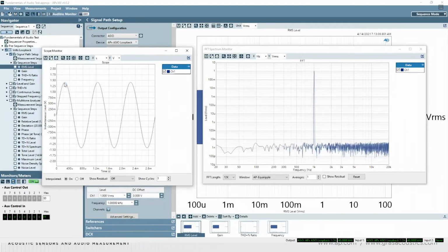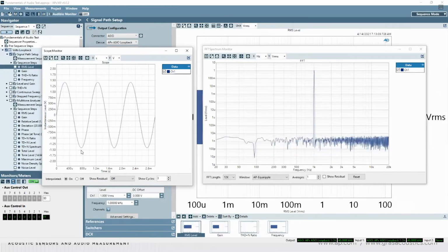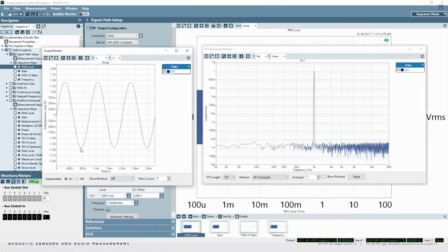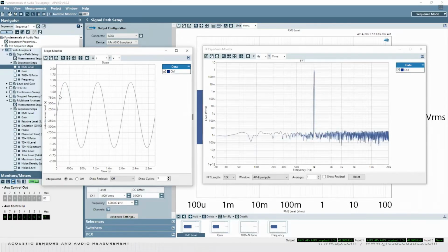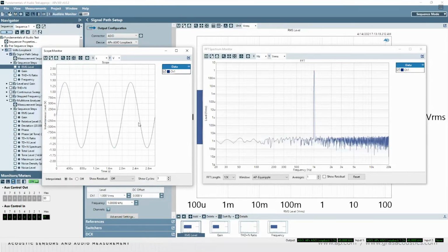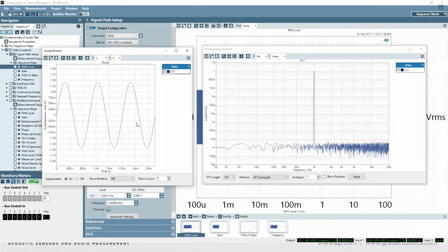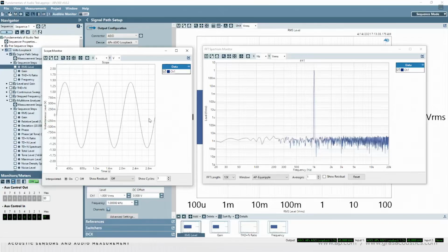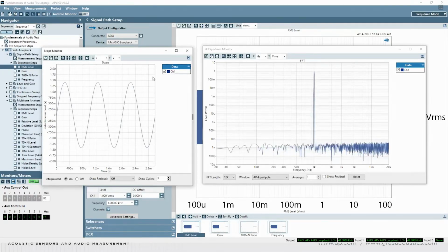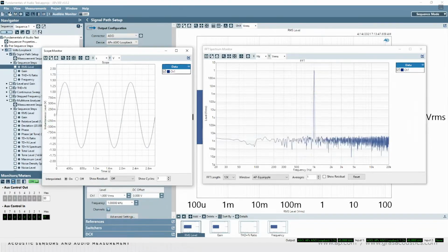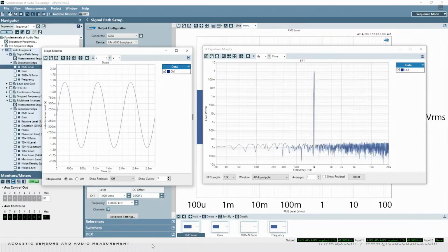The peak to peak value, which is from the maximum positive extent to the maximum negative extent, is of course just twice that amount. The RMS is, if you will, the area under the curve. Or another term that's a little bit obscure but explains what's going on is the heating power into a given resistance. That is to say, if you drove this signal into a given resistive load, how much would that load heat up? And that's described by the RMS energy of the signal. But volts is, I'll say, at the root for test instrumentation.